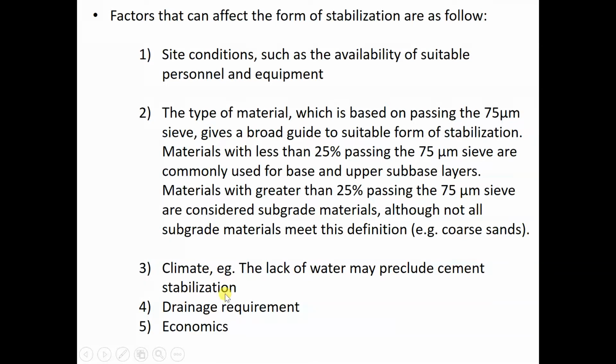Third, climate. For example, the lack of water may preclude cement stabilization. For cement stabilization, we need water to do the operation, because cement only reacts with water. If there's no water, there's no reaction, so it cannot do any strengthening of the pavement.